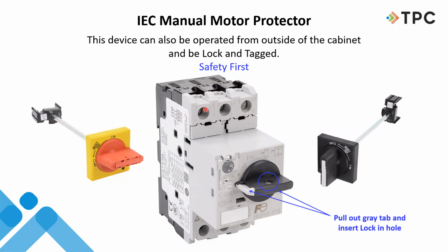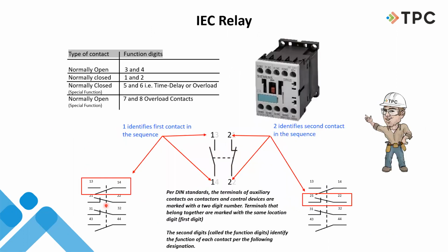And so our numbers are the same here, back to 1, 3, and 5, same way down here. The scheme is the same for all their stuff. Now here's what we're talking about on these relays and contactors. On a relay, this is really important to know what things do, and we've talked about this. 3 and 4 are normally open. 1 and 2 are normally closed.